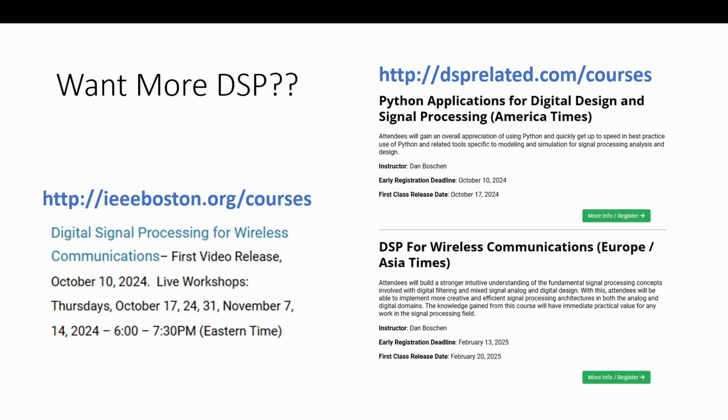And then DSP for wireless communications is more from the ground up, with more time with me to really understand the Fourier, Laplace, and Z transform and how we build that up into very high performance filters and multi-rate signal processing and the FFT and things like that. The DSP for software radio is now top down where, hey, let's implement carrier tracking loops. Let's go through a QAM modem. Let's build it in that simulation, and timing recovery and AGCs and all the things you would see in the software radio with the loop models and the benefit of the loop models.